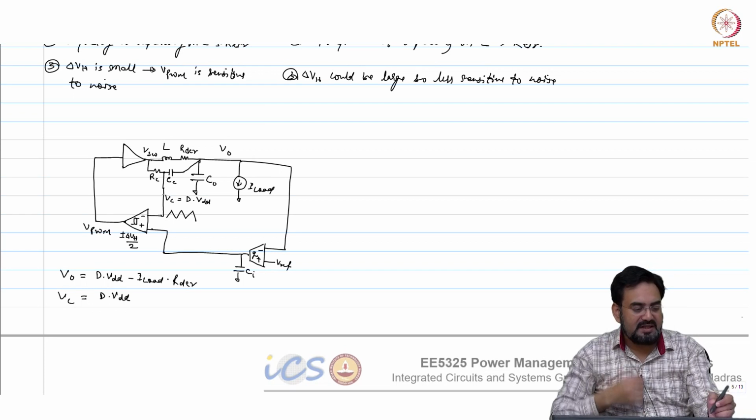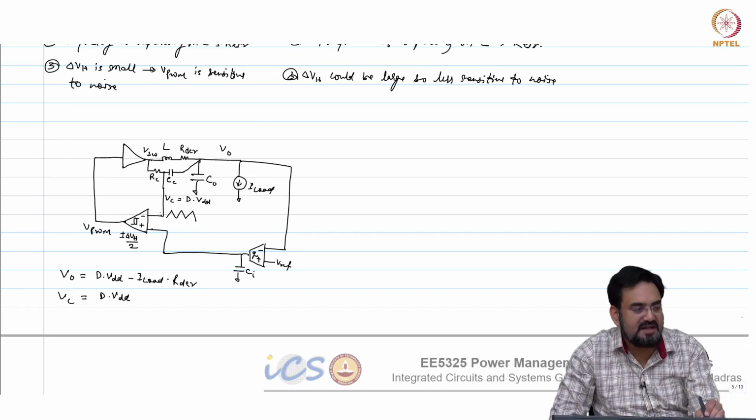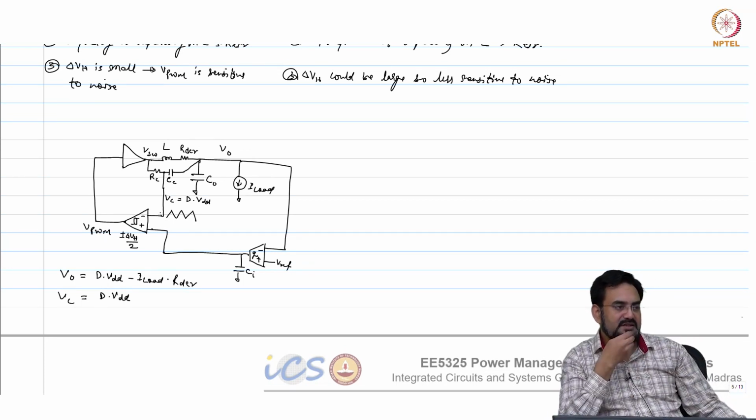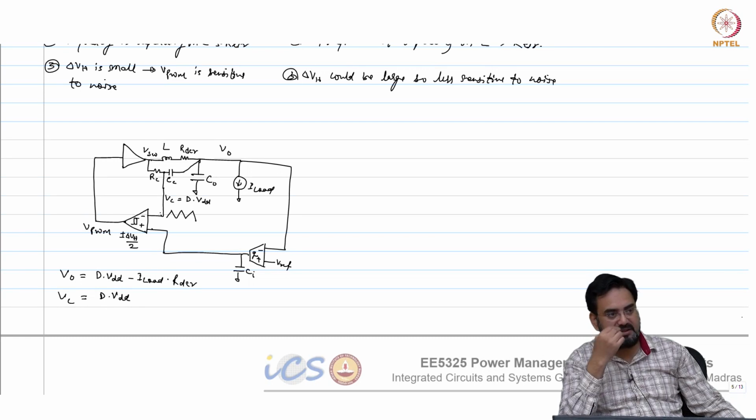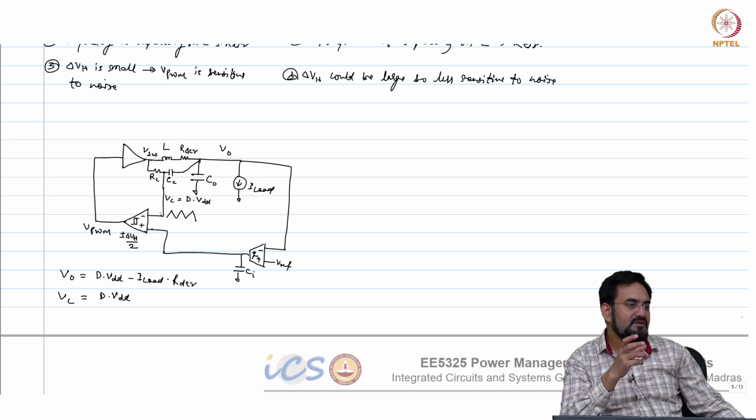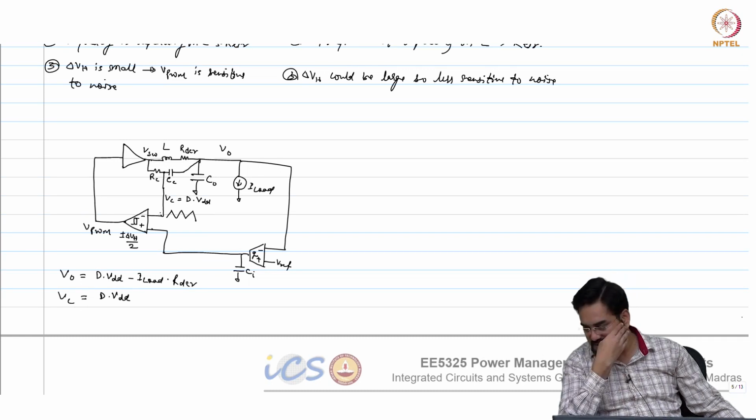And the other thing is, I am trying to keep this delta Vh large here due to noise reasons. So my output has to wait until that time before your comparator trips. So this large Vh window degrades the transient response. Regulation can be done with the integrator, but transient cannot be improved. So is there any other way I can improve both regulation and transient?